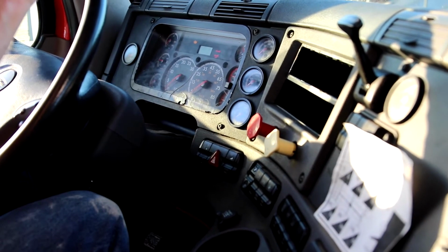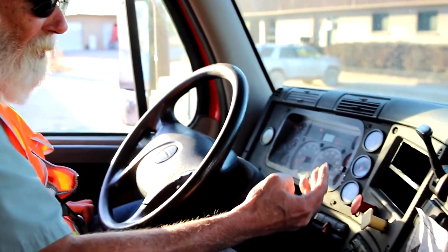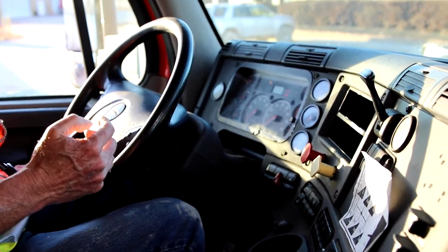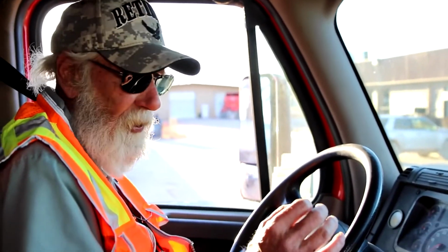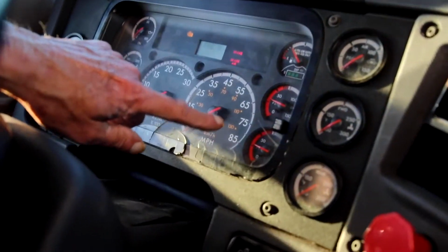Notice that one did it one at a time. So like I said, watch your brake valves. Make sure they both pop out. If you help these valves out, that could fail your test. And I am down to about 25 pounds of air pressure.